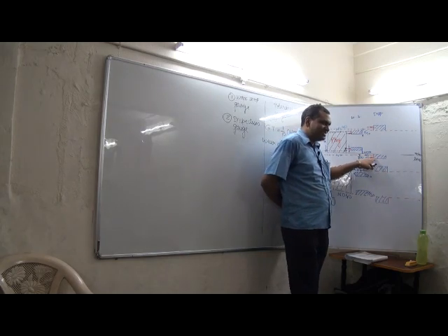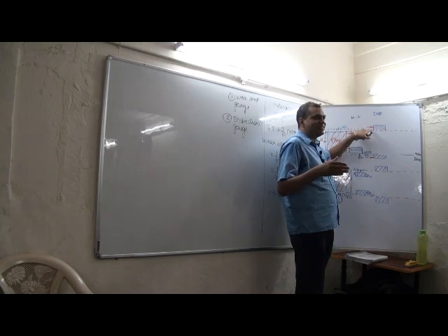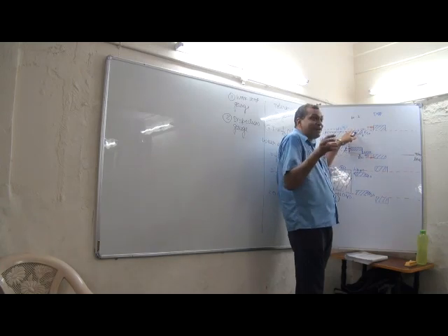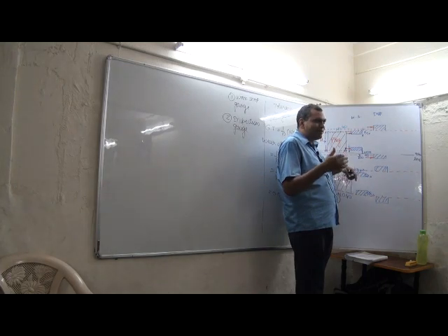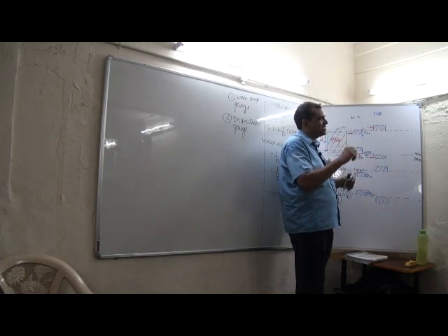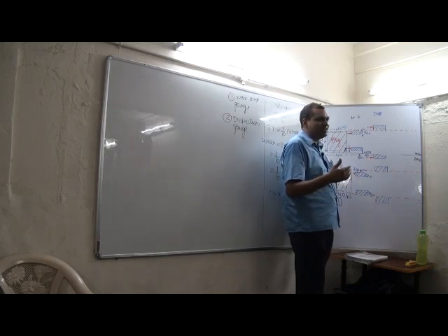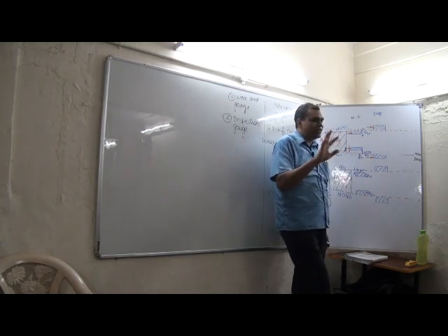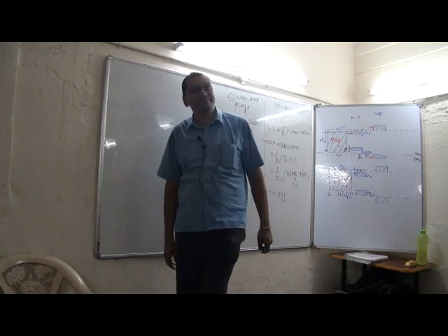Now see the next sentence. Since these inspection gauges are already slightly inaccurate. This is an inaccuracy, because we are accepting the bad parts and good parts. We are accepting bad parts and good parts, so it's inaccuracy. That's the reason we don't provide any wear allowance on the inspection gauges, because the gauges are already slightly inaccurate. We don't provide any wear allowance on the inspection type of gauges. Only workshop type of gauges we will provide.